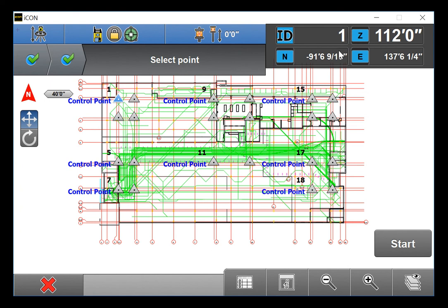A common error encountered is the selection of an incorrect point. Be sure that the point you select is the point you are about to measure in the field. By this time, it is assumed you know which point it is and have already walked over to it. Using Move and Search, you will want to ensure the total station is locked on the prism before clicking Start. Once lock is gained, click Start to begin measuring.